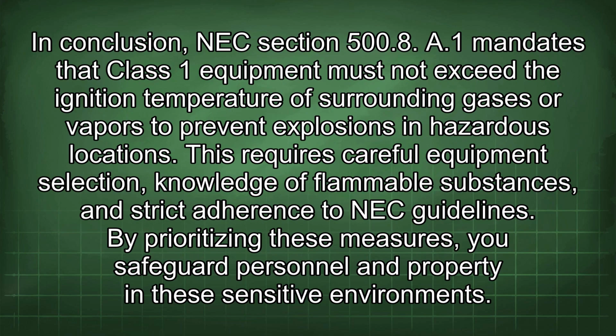In conclusion, NEC Section 500.8(a)(1) mandates that Class 1 equipment must not exceed the ignition temperature of surrounding gases or vapors to prevent explosions in hazardous locations. This requires careful equipment selection, knowledge of flammable substances, and strict adherence to the NEC guidelines. By prioritizing these measures, you safeguard personnel and property in these sensitive environments.